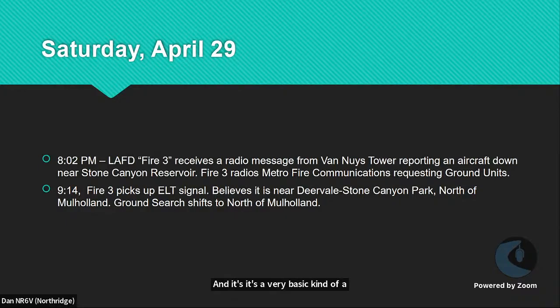Newer aircraft have 243 megahertz AM, and the latest have 406 megahertz AM, and the 406 radios have, to some degree, data included in the signal and are monitored by satellite. So the 406 is the ideal thing to have. This was an older aircraft, although a lot of the avionics had been updated. They were still using the